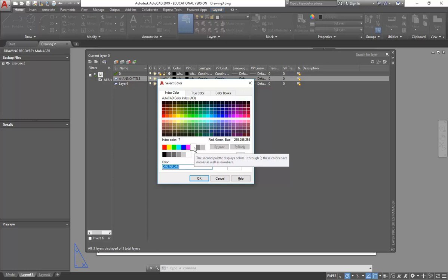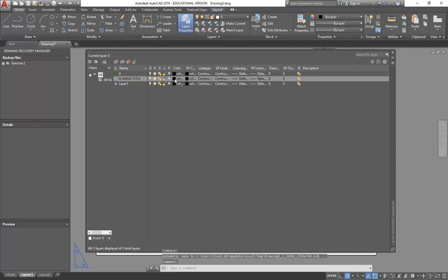Look, nowadays you can print white, but in the old days you really couldn't, and definitely with AutoCAD, you wouldn't want that. So essentially, if something's white on the screen, it prints black. If you're drawing on a black background, which is common in AutoCAD, then you'll draw white lines, but you want them to print black. So again, black and white in AutoCAD are the same colour. When you choose white on a black background, it'll be white, but when we're drawing on the page, that'll be black. All the other colours are the colours you'll see. And text is generally white, so I'm not going to change that colour.